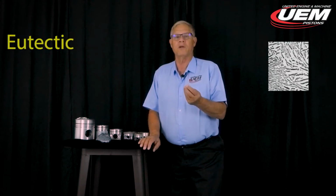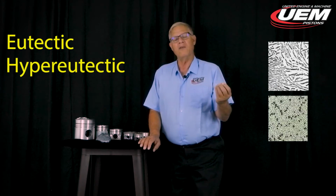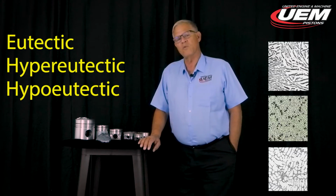So we have three conditions. We can have a piston at the eutectic point, we can have one over, a hypereutectic, or we can have one under, a hypoeutectic. So these characteristics will either improve the thermal properties as we get more silicon in, or it'll lower it, but it'll improve its ductility.